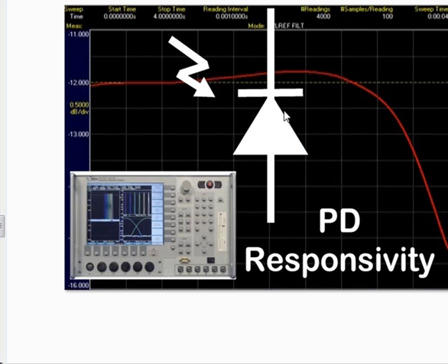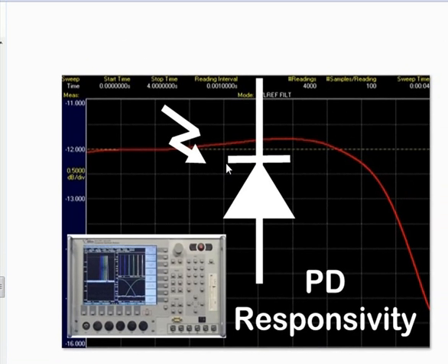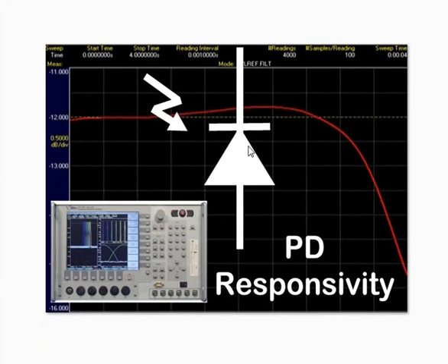The peculiarity of a photodiode is that when light falls on it, it starts conducting in the reverse direction also, only when the light falls on it. So in the multimeter's diode test, it will not show a reading in either direction, but you have to follow certain tricks to test this photodiode.